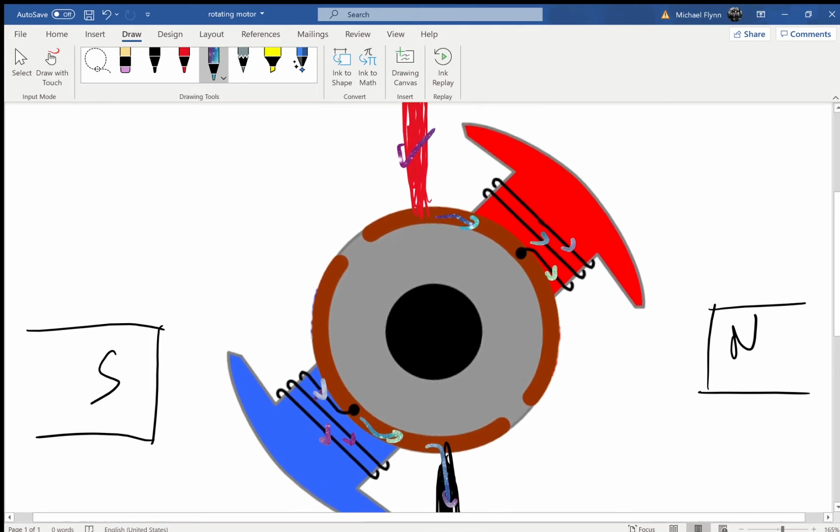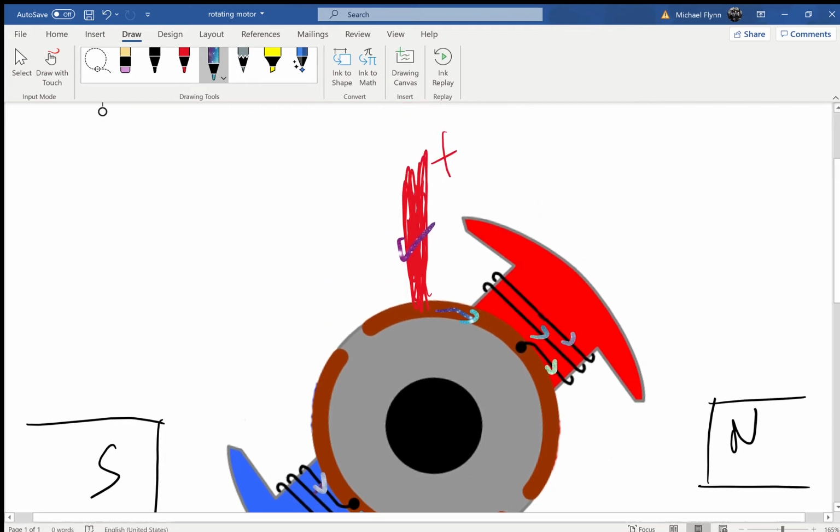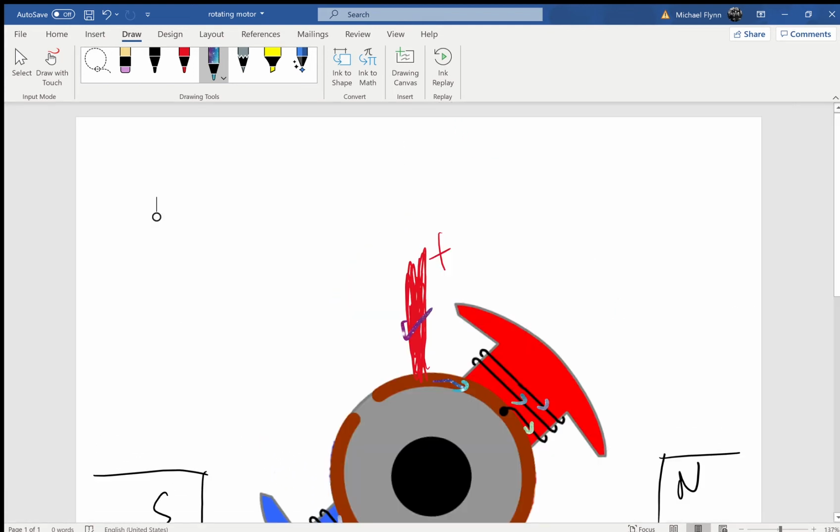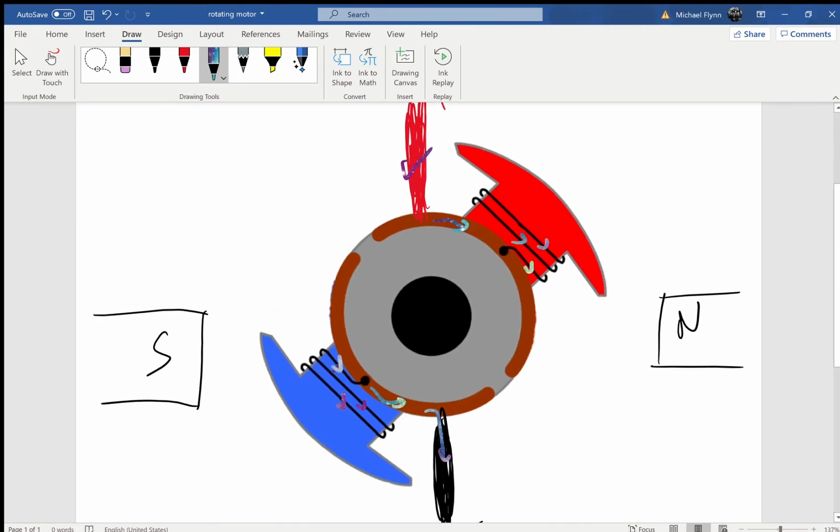Okay. Now, it's really important that the motor is able to do all that. Like you need to get, the power has to go in and come out. It cannot be stopped anywhere inside the motor, right? So there's just basically a coil wrapped around an armature, and the deal is that this armature is free to rotate. Okay, now I'm going to use my right hand rule for solenoids. Okay, my fingers of my right hand wrap around the front of the coil, okay, which come down the front face. My thumb will point towards north, so that would make this a north pole and that a south pole.